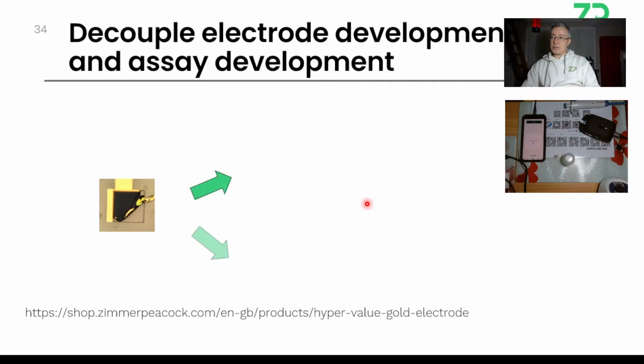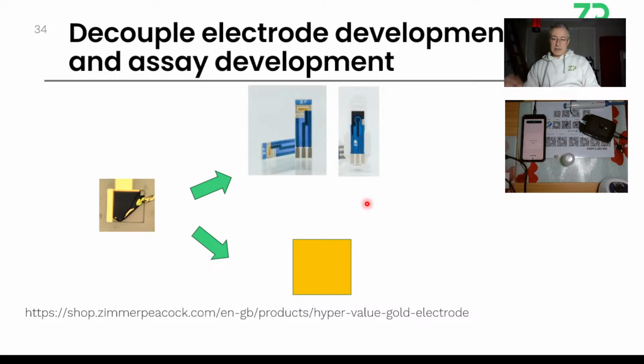This is the strategy part. I don't think you will get this on many other channels on YouTube because there's no one else really talking about, let's say, commercialization of electrochemical sensors. Split the assay apart. Work on the gold electrode. You've got a PhD, let's say it'll take 3 years, so work on your gold electrode. And you've also got assay and functionalization that you want to develop. Work on low cost, easy to obtain electrodes that you can just use, destroy, make mistakes.